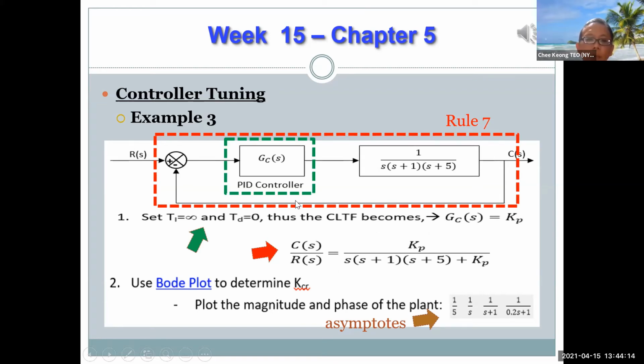But if you do an open loop transfer function, it will be Kp multiplied by this whole transfer function, right? So Kp depends on what the value is, but you know that there is 1 pole, 2 pole, 3 pole. So 1 pole is here, 2 pole is here, 3 pole is here, right? Because this factor here is normalized to 5 over 5, so S over 5 plus 1, or S over 5 is actually 0.2S plus 1. So the 1 over 5 is a result of bringing out the 5 over here, right? So this is 1 over 5. So basically your DC gain is 1 over 5. The rest of the asymptote is just as follows. So if you were to plot them...